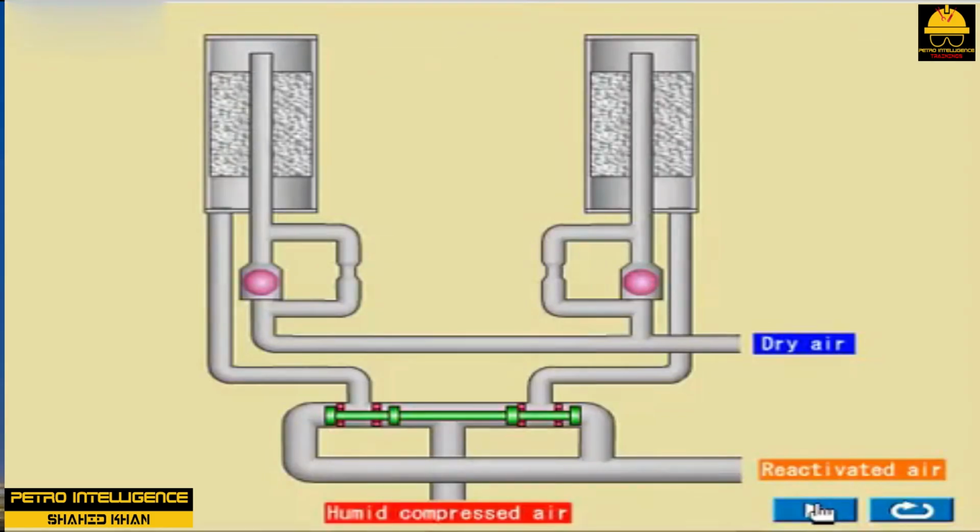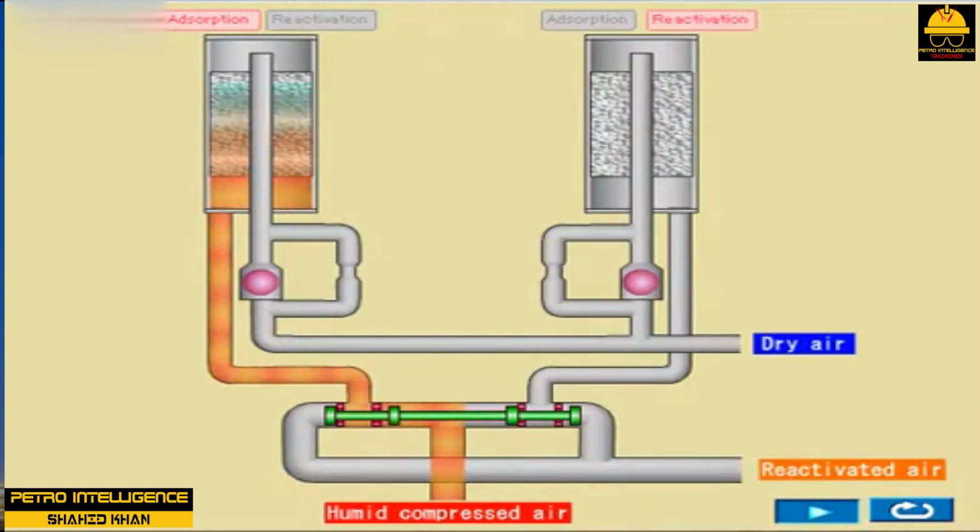stream. In some cases, when the solid becomes saturated, it is removed, thrown away, and replaced with a fresh, dry solid. In others, the solid can have the vapor removed, usually by heating. This method is called regenerating. The choice of method depends on the economics and time involved. A regenerating gas dryer usually consists of two vessels, beds, containing a granular solid. The solid is specifically chosen for its high adsorbency of the target vapor and ease of regeneration.